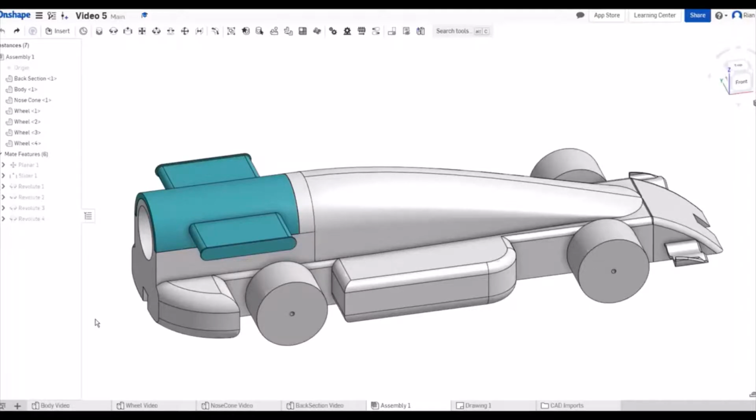Yes, another kind of slightly annoying feature is that we have exclusion zones around the wheels. So the front wheel, especially at the back of it, there's a very big exclusion zone, but in F1 cars you want a small exclusion zone so that there's no time for the air to converge around at the back of the wheel before hitting the side pod.